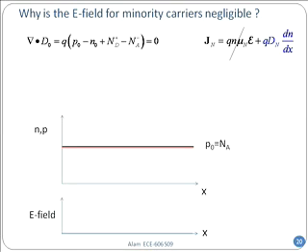Now, in equilibrium, I can also say that the minority carriers, which is the number of electrons, is equal to Ni squared divided by Na in the extrinsic region, right? I'm assuming full ionization, not in the freeze out or intrinsic region. Okay. N naught is a very small number, right? For example, if P naught is 10 to the power 18, and if it is in silicon, what is N naught? 100, because Ni squared is 10 to the power 20. And so, N naught is actually a tiny, tiny number. Fine, but it is flat, uniformly doped, and together they make the electric field zero.